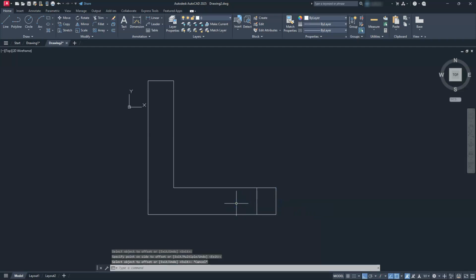Let's escape out of here and go back to the offset command. Remember, we can simply hit the enter button on my keyboard and it'll take me back to the last command. I'll type in 20, and then I'll do the offset here. All right, so now I have those two edges set there. We do have a radius that is located here, and that radius should be 10.